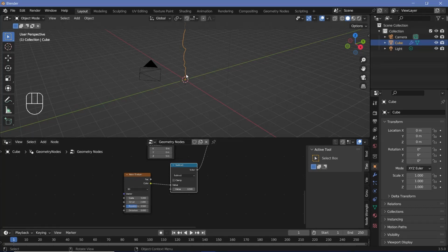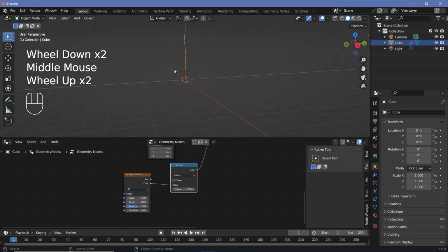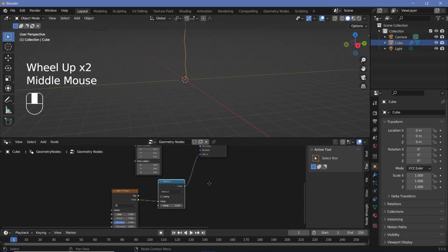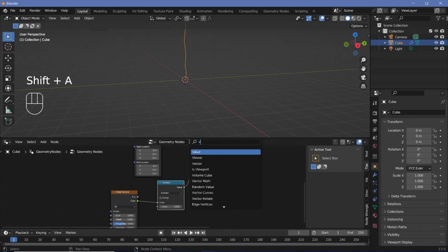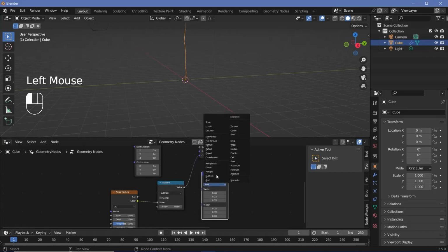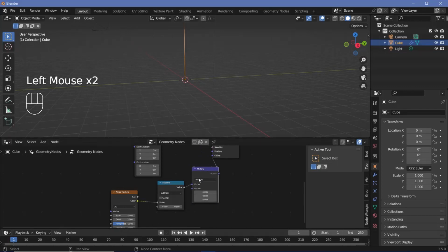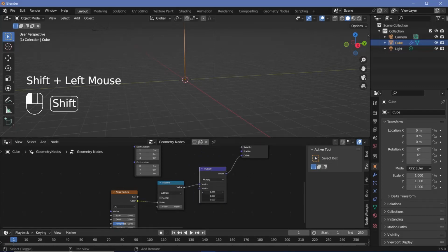The second thing is that the effect is in two small increments, which makes it look more like lightning than nice wavy strands. So we'll just decrease the scale down to something like 0.4, and that way we get a much smoother curve. However, the strength is too less, so we'll press Shift A and search for a vector math node and change it from add to multiply, and then plug that in after the subtract value, and then increase the values on all of the axes to maybe something like 5.